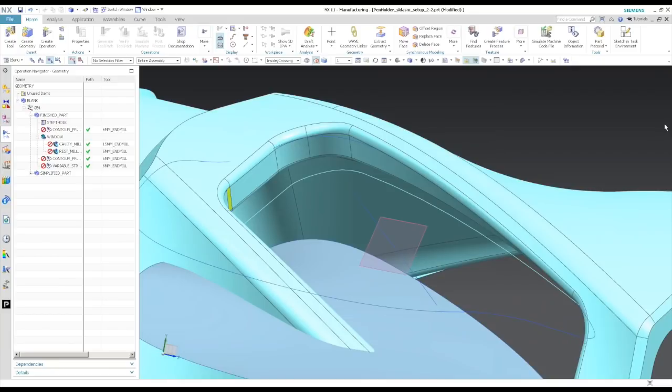Let's see who asked that. Yeah, that was for Brent. So I'll have that added to this sample. I would use the streamline, and you could do the helix type where it only engages once and then retracts once, so that'd be nice and clean. But it would be a stitch type toolpath unless you had a form cutter or a radius cutter.